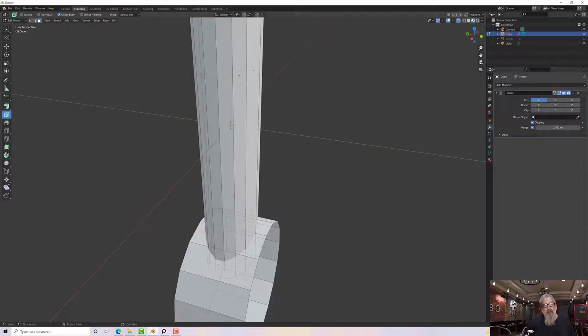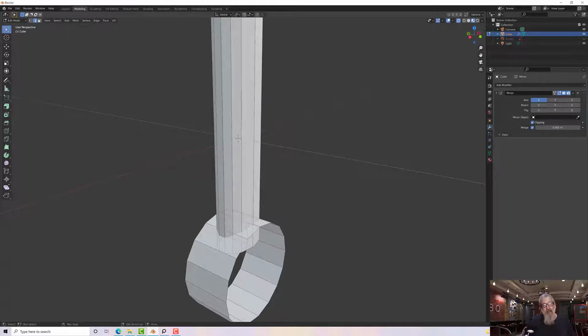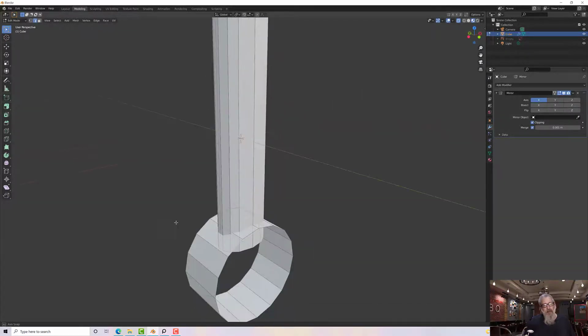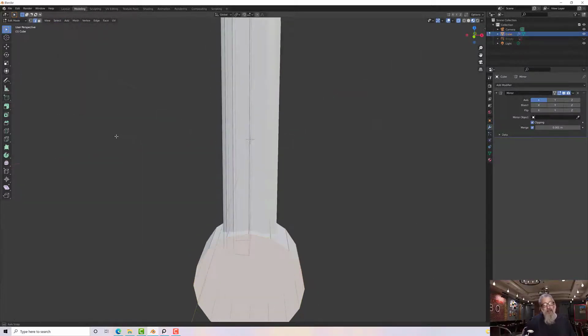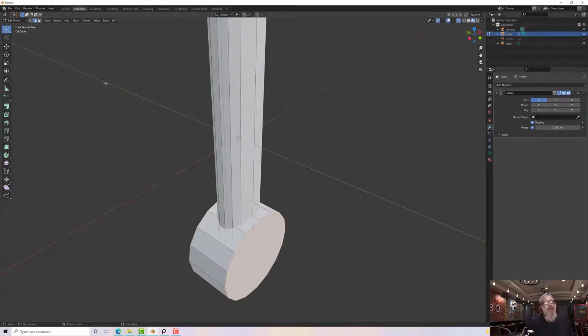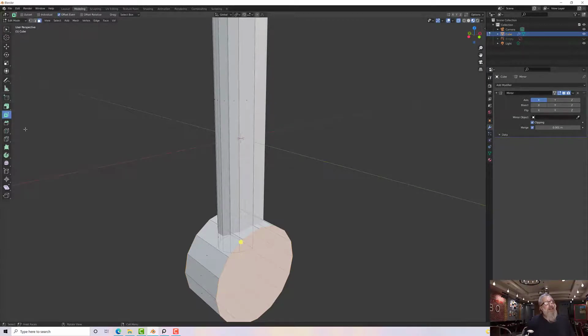And then we're going to have a look at these edges. So let's go to edge mode. I'm going to select this here. I'm going to go back to select mode so I come out of that inset mode and select the loops. So it's select and edge loops. I'm going to use the F key to fill those holes with a polygon. And now if I go to polygon mode, I'm going to try that inset again. And it's still doing it.